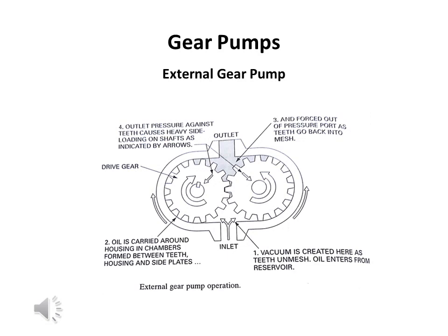Now the driving gear is connected with the motor. Whenever we switch on the motor, the driving gear will start to rotate. In between the gears there will be an oil film. Whenever the motor starts to rotate, both gears start to rotate in opposite directions. When the gears are moving away from each other on the bottom side, the gear teeth are moving away from each other.